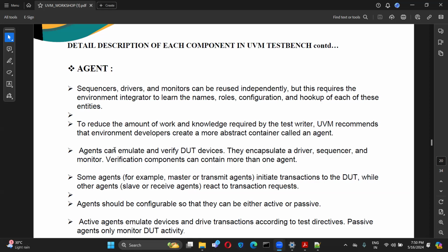So our generation always looks for customization, right? You want to make it either this way or this way, a single thing you want to use for multiple purposes, basically. In the same way, here also the UVM agent is always recommended to be configurable. From the env you should be able to control whether you want the active agent or the passive agent, because in most cases the same agent can be reused in different projects, right? So if there is a configurability control with you, it is easy for us to reuse it in different requirements. That is the main thing you have to focus on here.